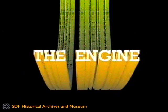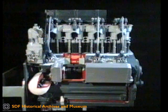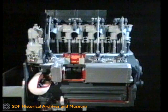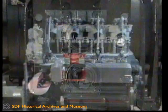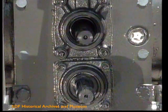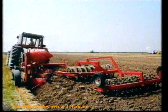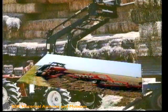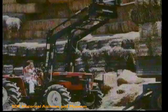The engine. The engine is the heart of an agricultural tractor. In fact, it has to not only provide the mechanical power necessary to generate the tractive force to the wheels via the transmission, but it must also transmit the motion to the power takeoff in order to operate the external implements. It must, furthermore, provide hydraulic power for the front and rear lifts, for the external implements, for the hydrostatic steering, and all the other integral hydraulic systems.